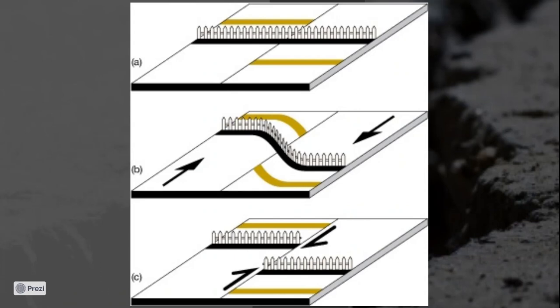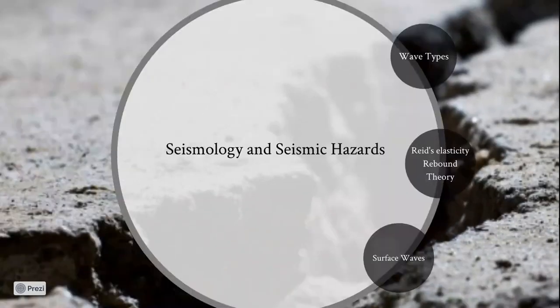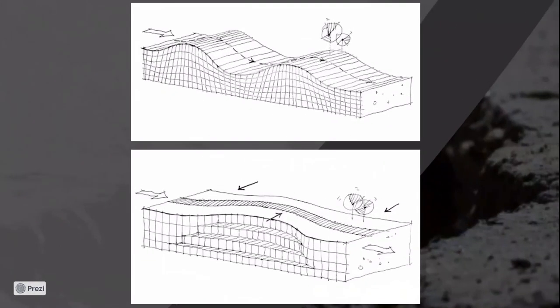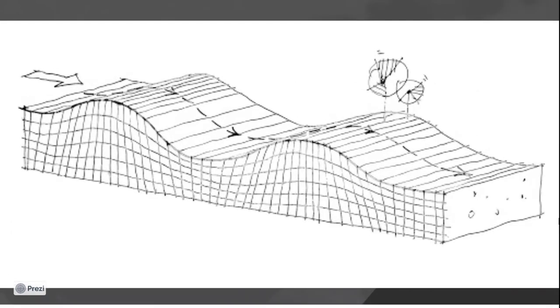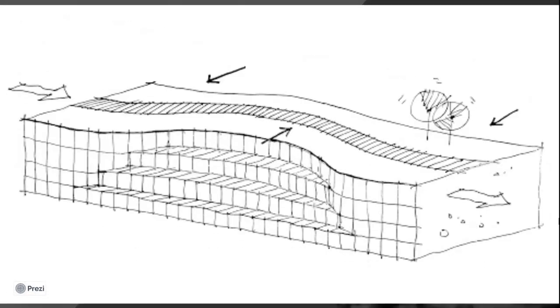waves and ground motion. Finally, talking about the surface waves, they are easily distinguished on the seismogram owing to their high amplitude, and they are responsible for further damages caused by earthquakes. There are two types of surface waves, starting with the Rayleigh waves. It spreads vertically and horizontally in ripples or form of rolls like ocean waves and can be most noticed in large spaces. The second one is the Love waves. They move on a horizontal plane, causing damage on the foundation of the structures. They also travel faster than the Rayleigh waves.